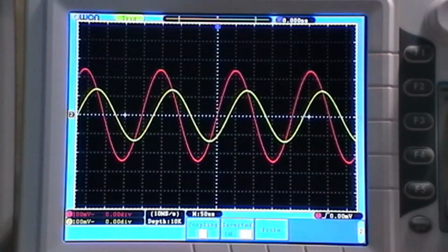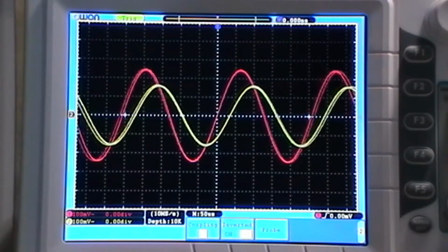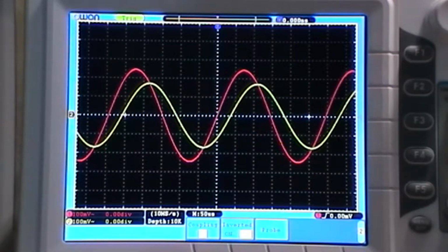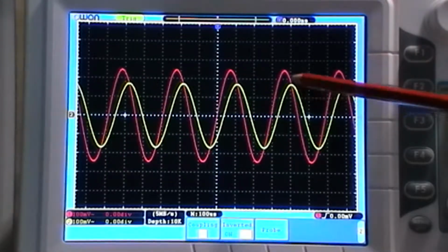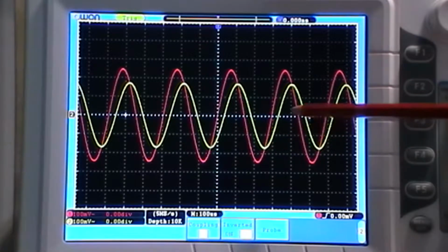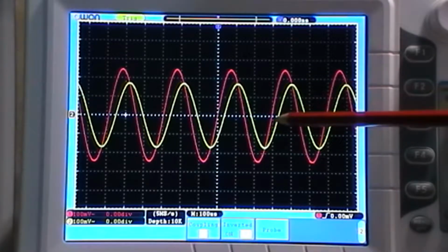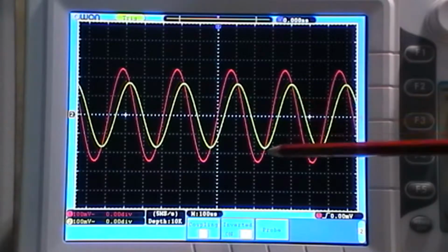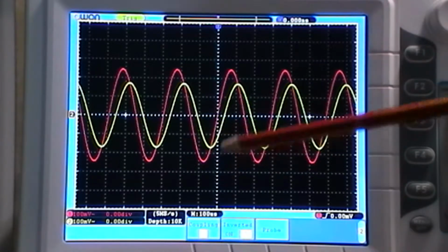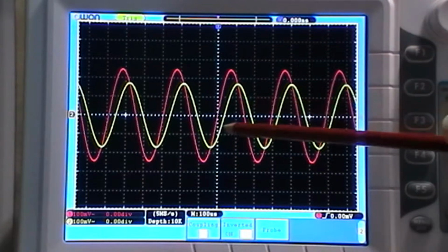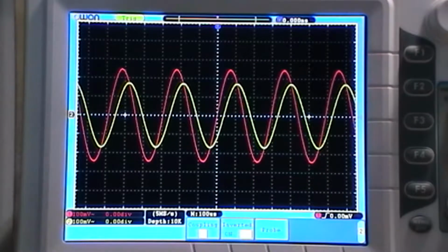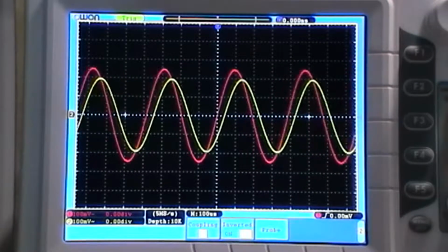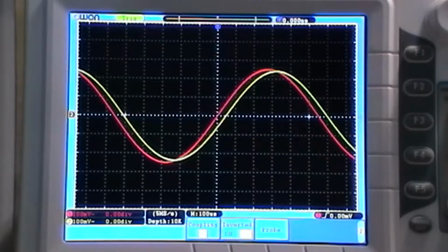So we come back down to the 3.4, which is about where the signal is starting to be at that -3 dB. Its supposed cut-off point, yeah, looks about the same as the other ones. Of course, the same sort of phase shift that we've got with all of them. So let's turn that back down to my 500 hertz,